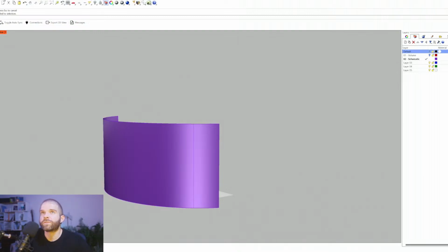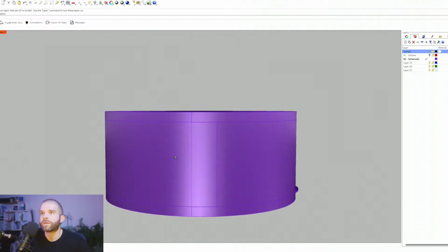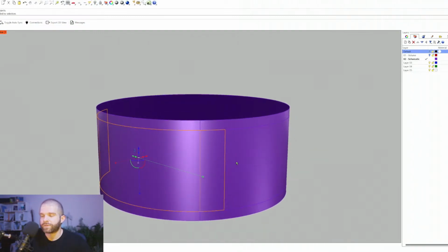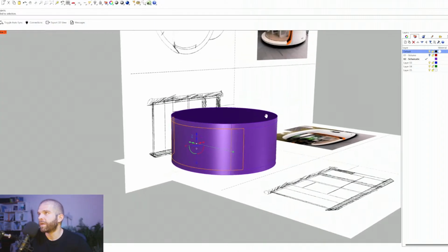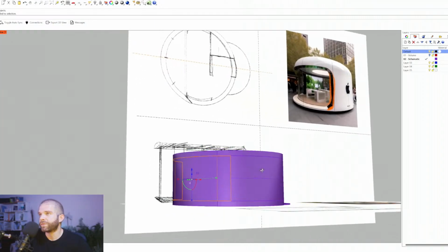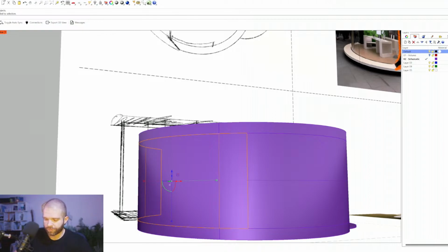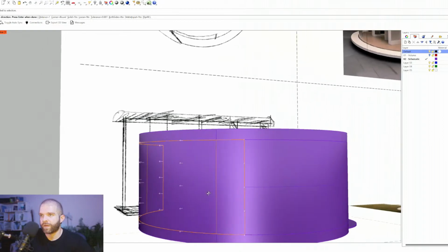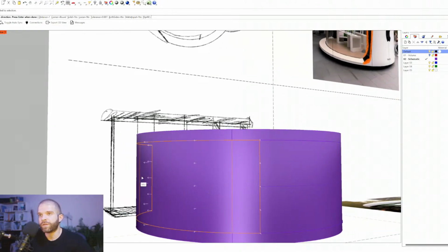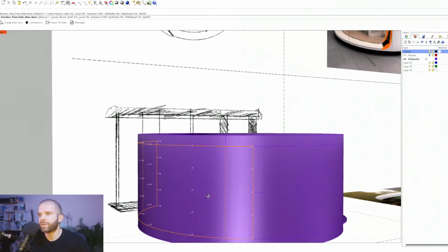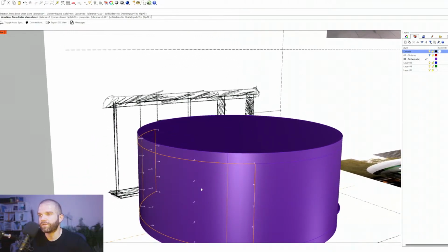Let's bring everything back, because that face, that little band, essentially follows that same opening. So we're going to do an offset surface, and we see some arrows pop up. It's going to offset outward. We actually want it to offset inward, so we will just click on it, and it flips the arrows, and then we want to change the distance.